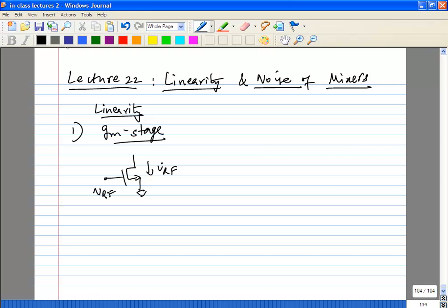But the thing to keep in mind is that, you can do two things. One thing is, increase the current, but of course you have a power limitation. So let's say you hit that point. The next thing you can do is start decreasing the size of the transistor to increase the V overdrive.